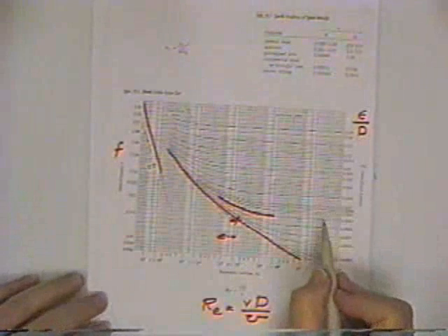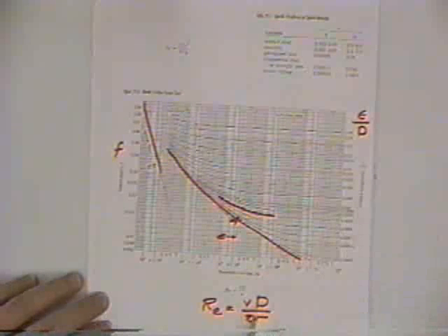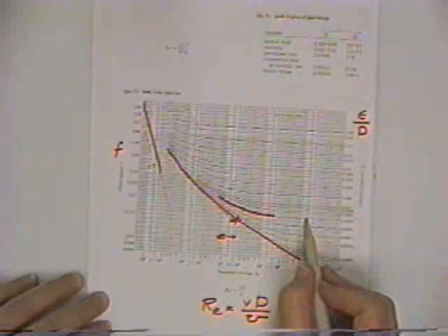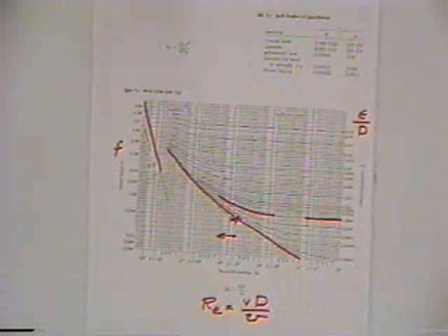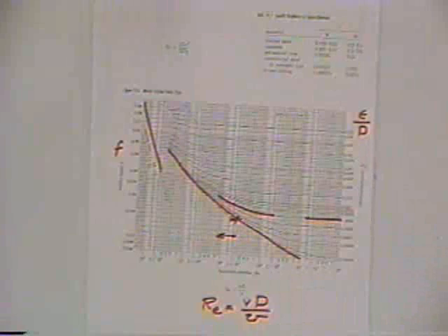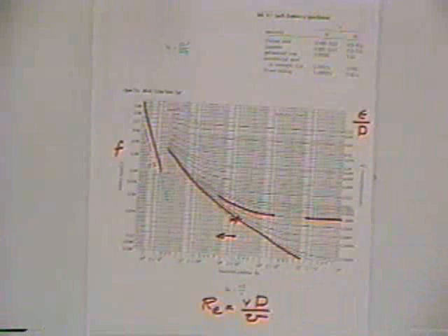But if the velocities get high enough, high velocity meaning high Reynolds number, these lines get horizontal, meaning that the friction factor, the frictional head loss roughness coefficient term, is no longer dependent upon Reynolds number. It's constant with Reynolds number, and then it's just dependent upon changes in pipe roughness far enough out. We call that the fully rough zone.